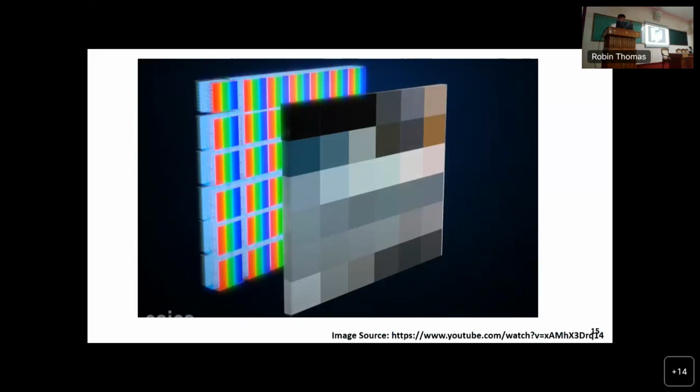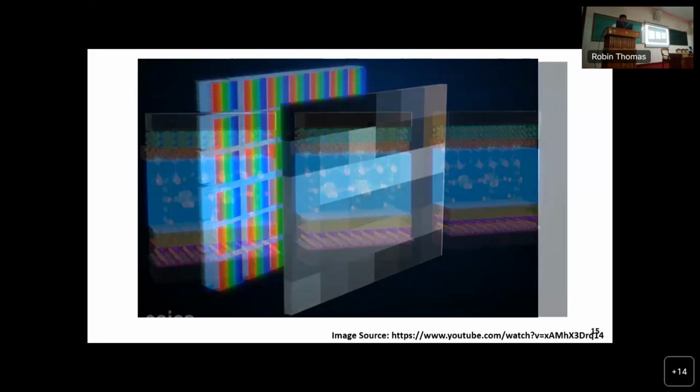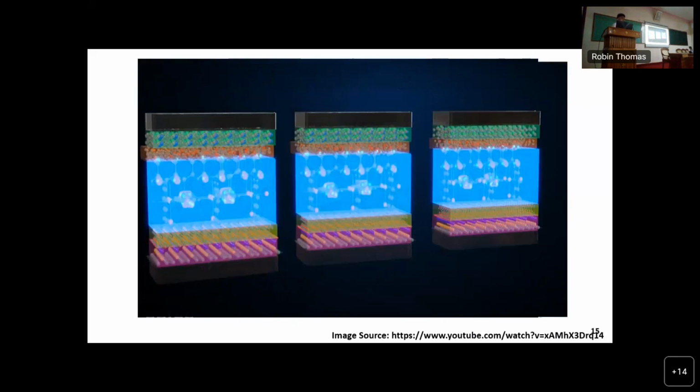But the question is, can we still modify or compress this display? Yes, you can. What else can we remove from this display? We can't remove the backlight, but we can remove the RGB filter. This is the possibility that we have. But how? We can construct different light-emitting OLEDs. Instead of an RGB filter, we can select red, blue, and green emissive organic LEDs. So how do you achieve that?